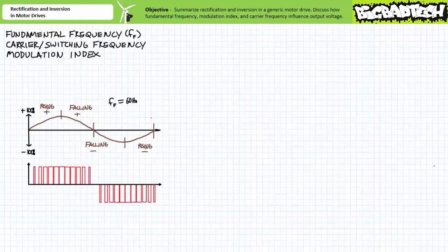To generate the negative half of the wave, it's the same song, quite literally in reverse, since polarity is changed. The inverter varies the duty cycle in a sinusoidal fashion from 0 to 100% to generate the falling negative section over 4.2 milliseconds. Then it varies the duty cycle in a sinusoidal fashion from 100 back to 0% to generate the rising negative section over the remaining 4.2 milliseconds.